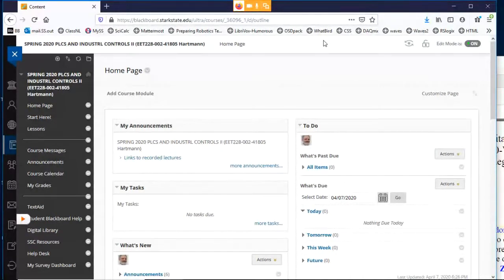Then go ahead and click on the save button quite often too. I haven't worked with this software very much yet, so with anything new, I want to make sure I save my changes so I don't have to rebuild everything from scratch because I did an oops. So I recommend doing a manual save quite often: click on accept rung edits and then the save button. Do that quite often. All right, so any other questions with that?